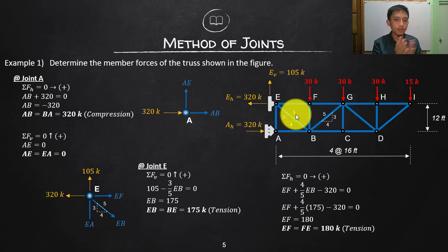If you have concurrent forces acting on a single point, let's say two or more forces acting on a single point, you can combine all of these and consider that as a single force, which is a combination of all of these acting forces, and we call that the resultant.